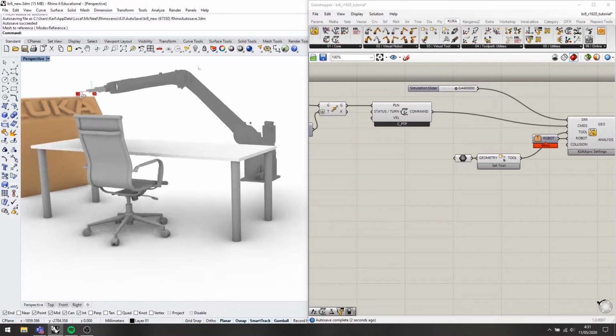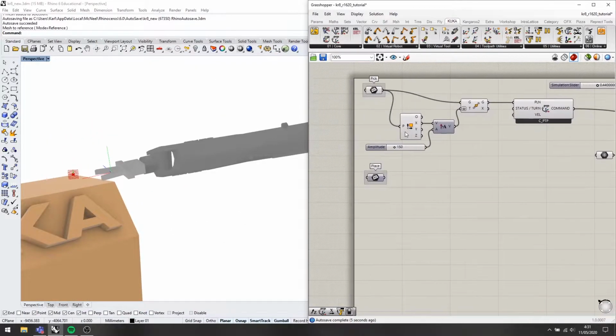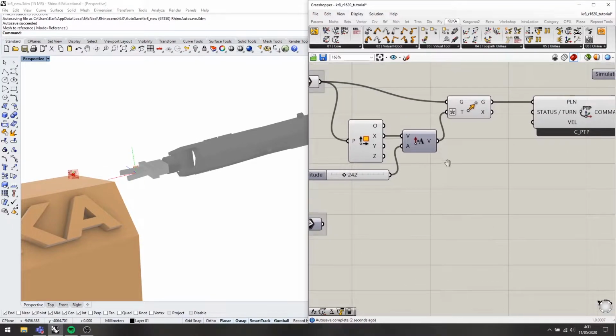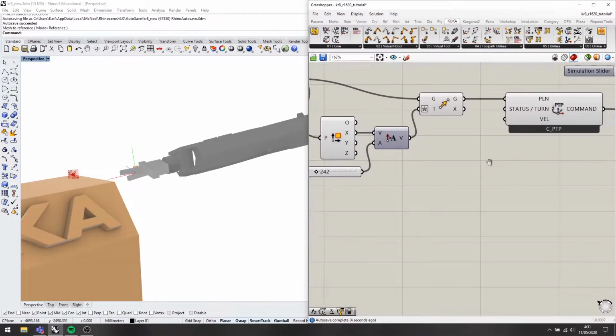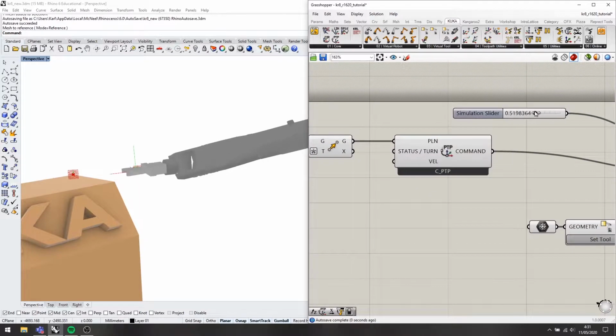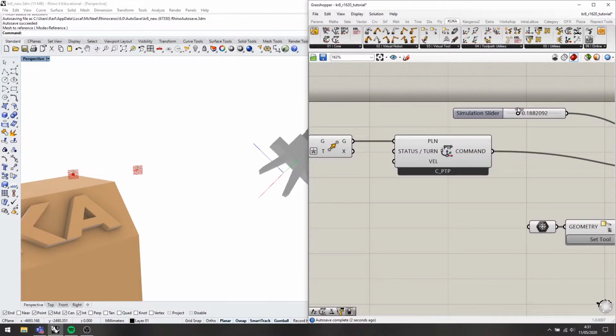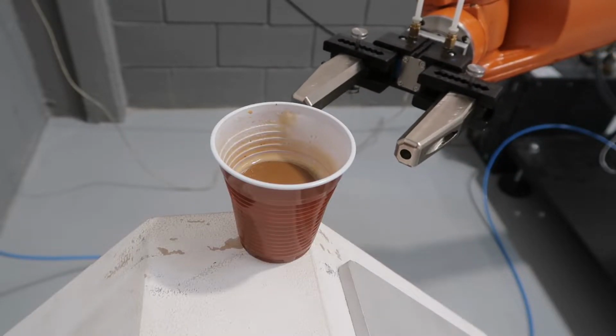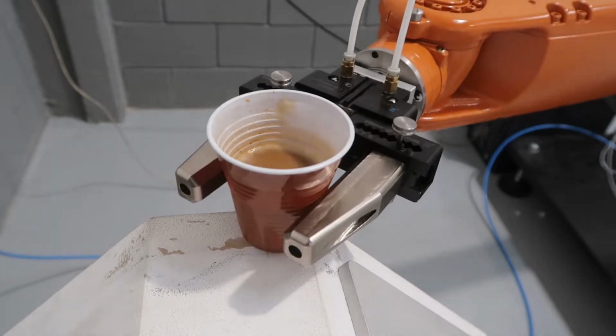We might even just move that back a bit further, so increase the 150, a bit back, and then the gripper stays clear of our stand at all times. Okay, so this is pretty basic. This is stuff we've done quite a few times on this channel. Cool, looking good. So now we want to do a linear movement into our cup.